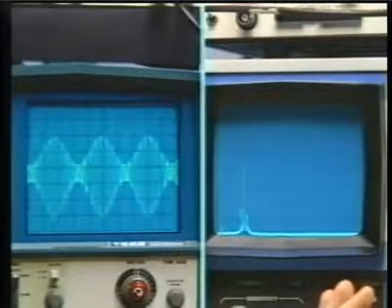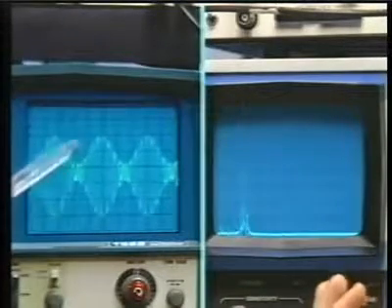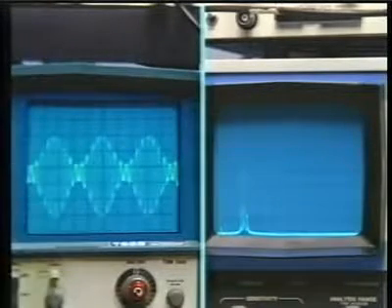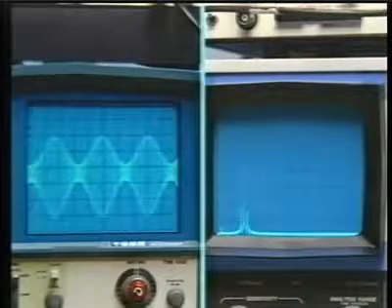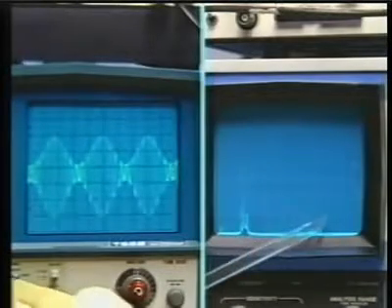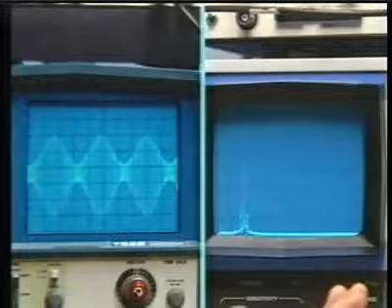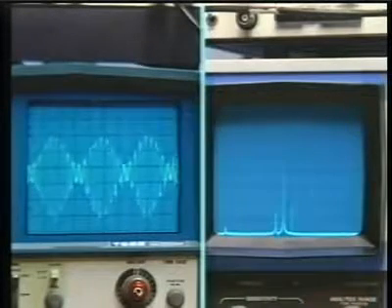This is actually called a ring modulator. It's very simple to multiply a signal by a square wave. It's just a chopping process. And so a square wave carrier signal is very convenient to generate, and then you simply filter out the higher order harmonics. All right, I'll go back to the scale that we had before.